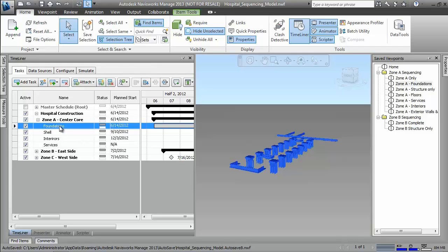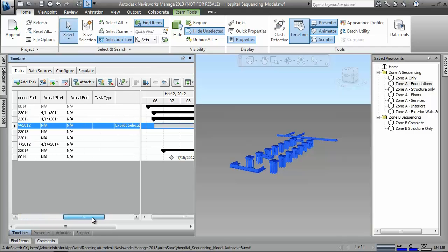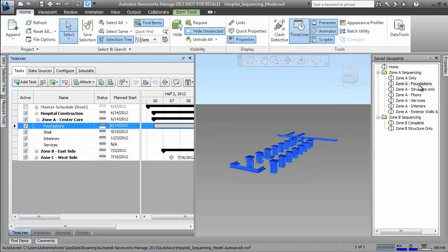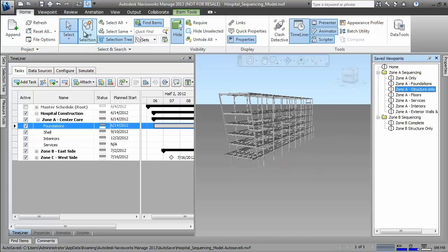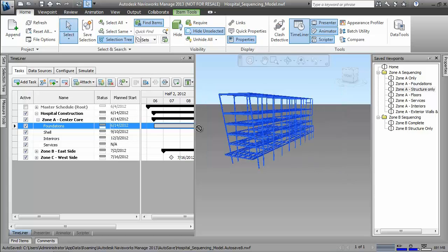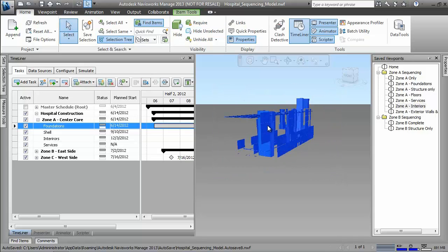The Autodesk construction solution supports workflows for creating project activities based on your categorization of the design data, which can be used to ensure the correct order of events, producing a skeleton schedule. With common tools such as indenting, moving, and grouping tasks right at your fingertips, creating a schedule here in the model environment saves time and streamlines the workflow.